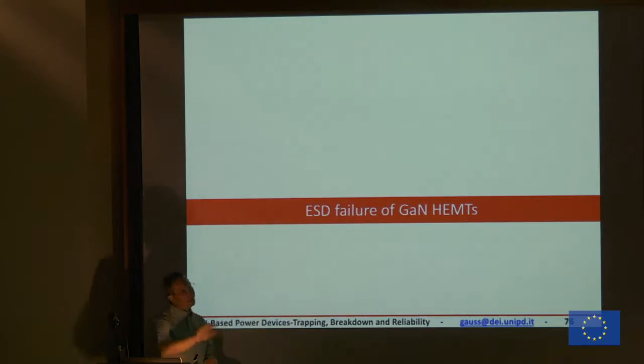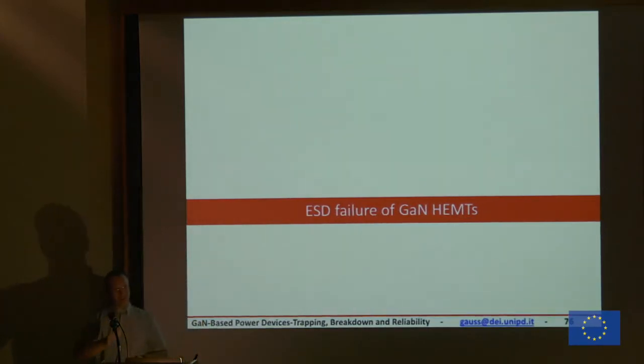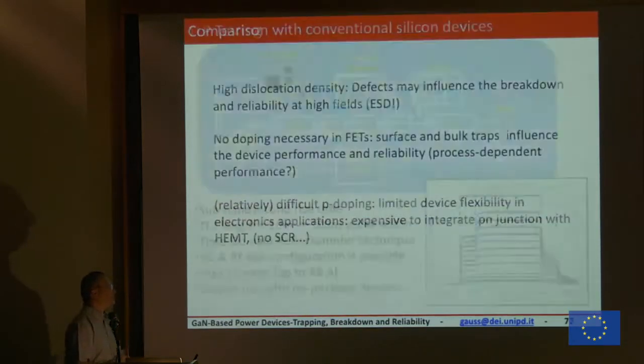All electronic equipment you have in your hand, telephone, computer, any electronic equipment has an ESD protection structure in order to avoid the discharge across the device. Even your USB port of your computer, whenever you connect your USB to your port of your computer, you are injecting charge. If you don't have an ESD protection structure there, your computer port will be dead in a few times that you do it. But this is another story.